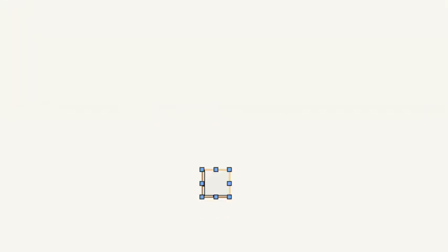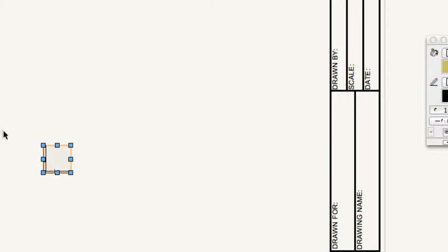Let's bring this back and let's do this. Let's select the leg, have it selected, and now you're going to select the mirror and make sure that mirror duplicate is selected. Come over here, hover around that corner, and actually let me zoom in just a little bit more so you can maybe see it a little better.